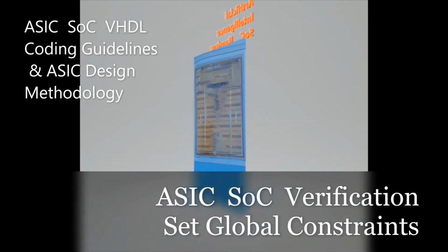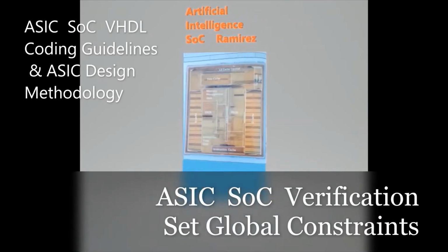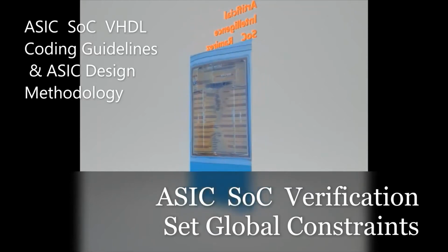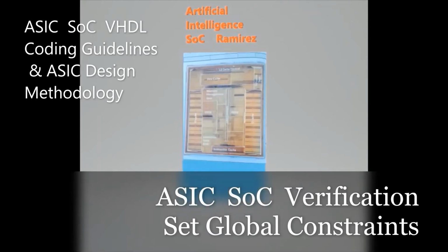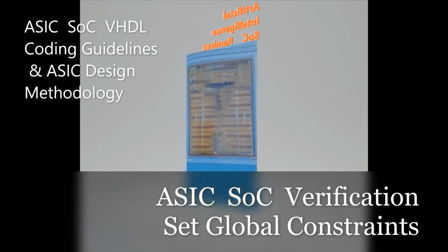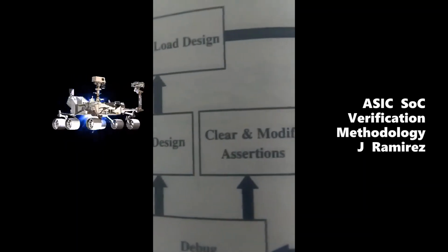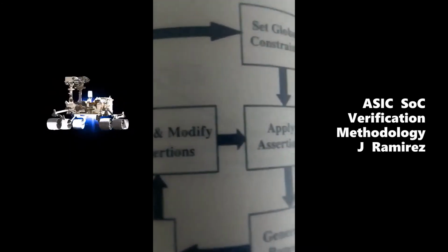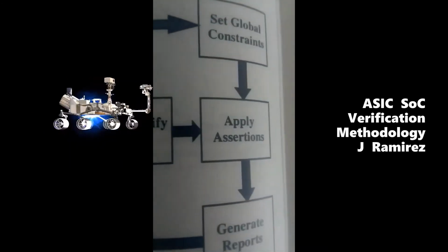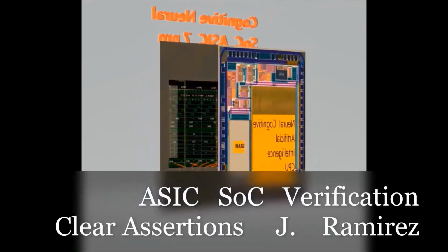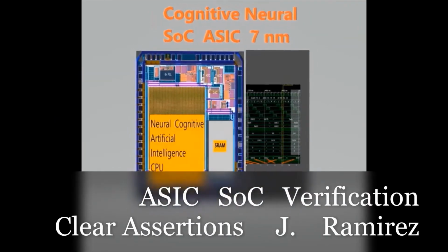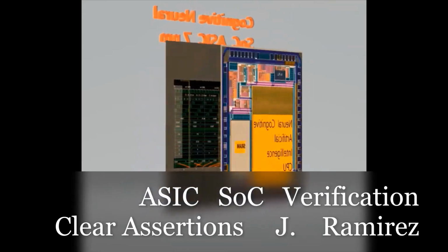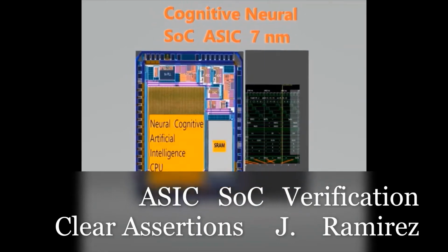This segment describes some of the coding guidelines. The system-on-chip ASIC design software models were written in VHDL. The basic software coding rule is that in order to obtain predictable results, code was kept simple. Therefore, the VHDL software models were written to guarantee that the synthesis would produce the desired result.